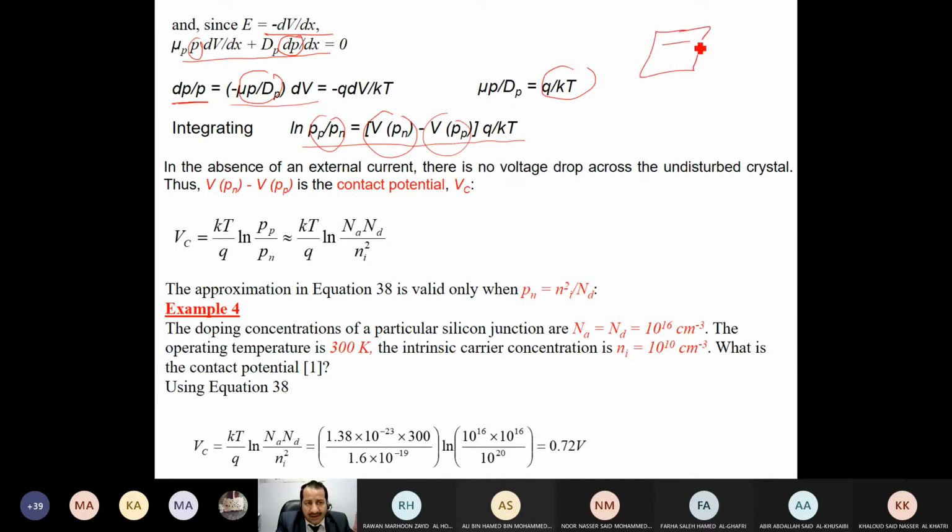You know, this is the cell. At the end, we have two terminals coming out, from which current is taken from these two points, positive and negative. If I define this voltage to be the contact potential Vc, then we have a formula for it. The voltage of the cell equals k, the Boltzmann constant, times T, temperature, over q, the charge of the electron, and then these concentrations. We can represent them in this way also. It's equivalent. Let's take this and use it in the next example.